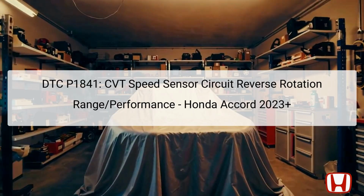The DTC P1841 indicates an issue with the continuously variable transmission, CVT speed sensor circuit, specifically relating to the reverse rotation range and performance. The CVT speed sensor is critical for monitoring the speed of the secondary shaft within the transmission. When the voltage signals from the CVT speed sensor and the driving conditions do not align as expected, the Transmission Control Module, TCM, identifies this anomaly, storing the DTC in the vehicle's computer system.